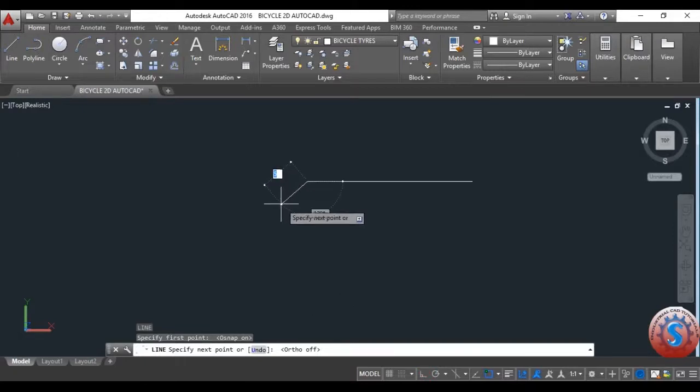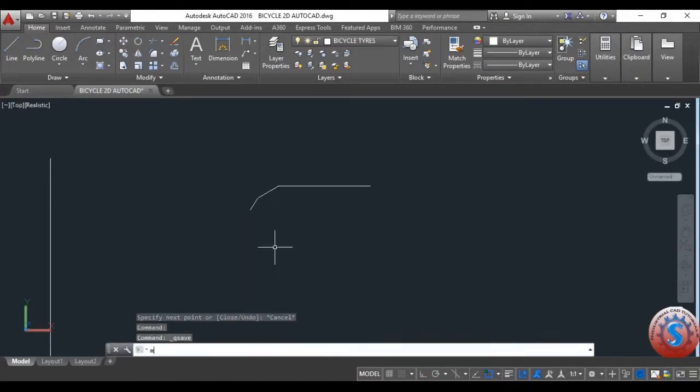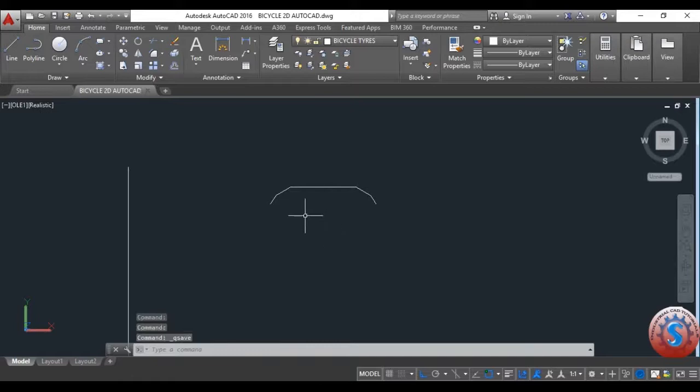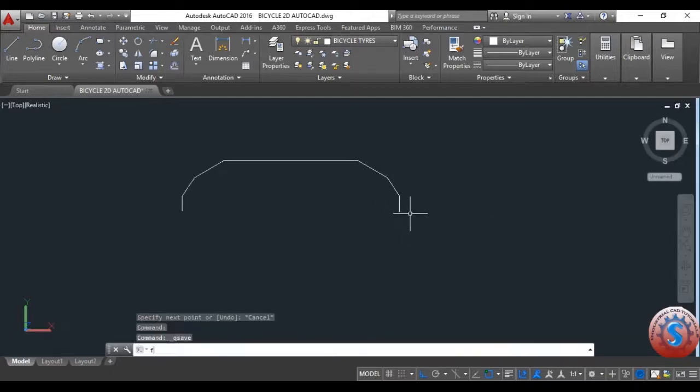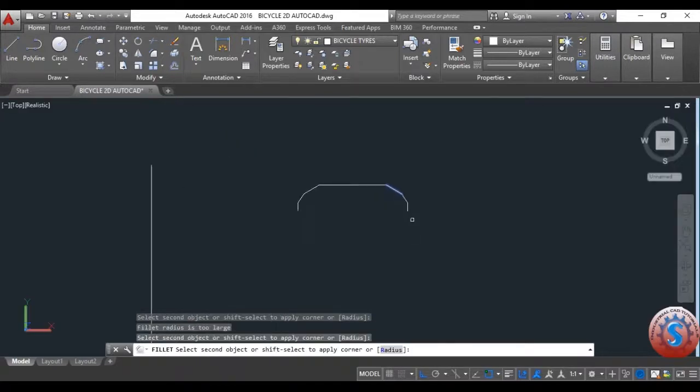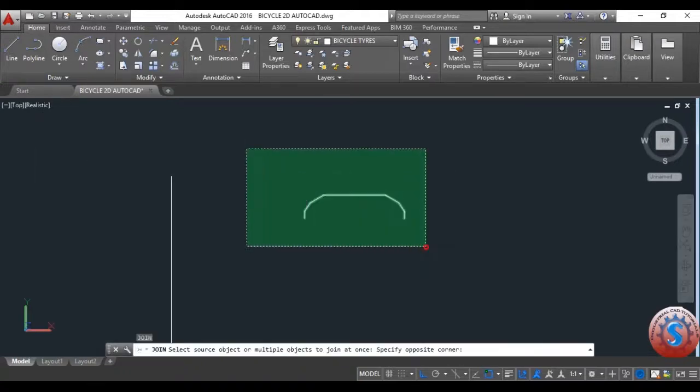and simply turn it off, and create like this, then enter, simply create and click on enter. You can also give the dimension exactly like this, and observe I'm giving this like this, and I want to give the radius of this. You can also give the radius of 25 as you wish, and then after that join with J enter,